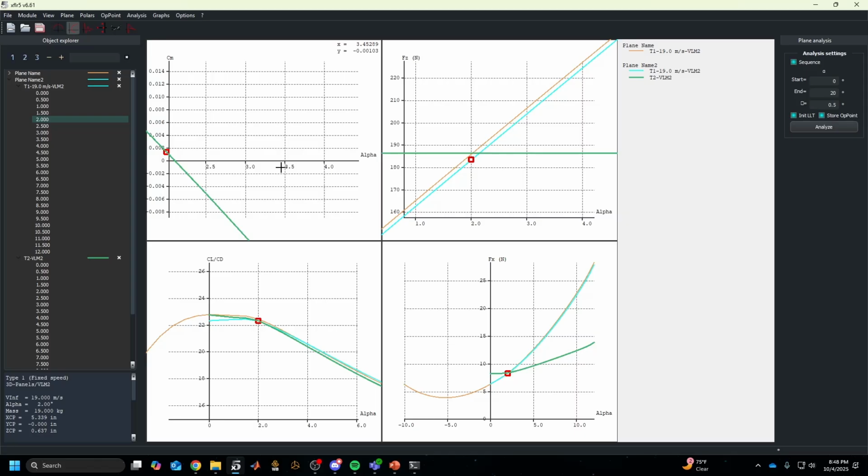Because if I make our wing angle of incidence 5 degrees and I go to my PDR and say, hey, we're trimmed out at 3 degrees, if I were in that audience, I'd raise my hand and say, so your wing is at 8 degrees, right? So if you pitch up by 5 degrees, you're about to stall. Okay? So keep that in mind.